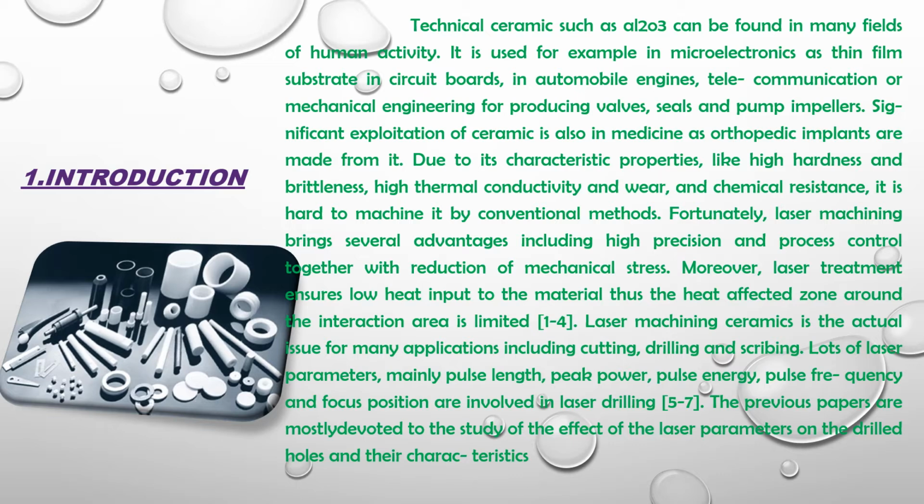Due to its characteristic properties like high hardness and brittleness, high thermal conductivity, and wear and chemical resistance, it's hard to machine it by conventional methods. Fortunately, laser machining brings several advantages including high precision and process control together with a reduction of mechanical stress. Moreover, laser treatment ensures low heat input to the material, thus the heat affected zone around the interaction area is limited. Laser machining of ceramics is actually used for many applications including cutting, drilling and scribing.